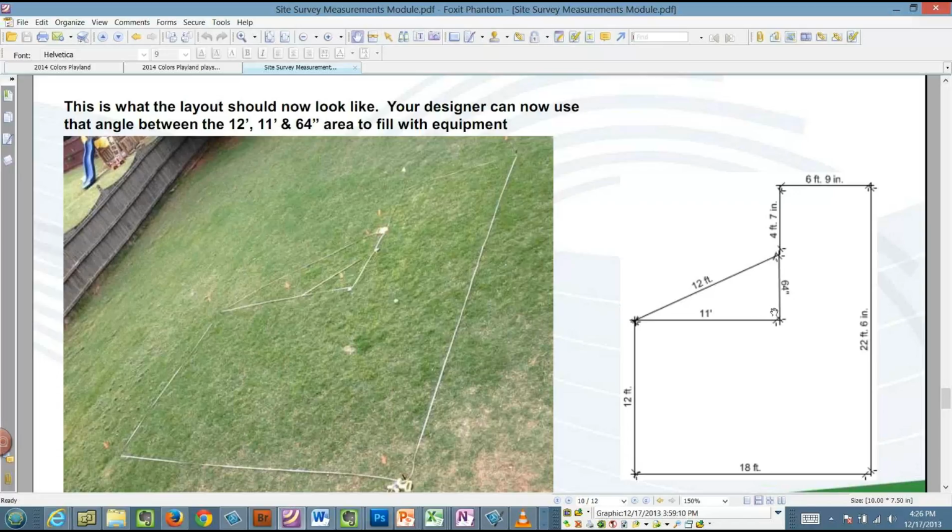You could visualize this if you wanted to, and assume what a 90-degree angle looked like without doing 3, 4, 5, but there's no guarantee. Okay. So if this weren't 3, 4, 5, and these weren't lining up properly, you would find that your measurement could be off. If this were off by a few degrees, you could find that your area measurement might be too short or too long. And again, talking about exacts, and when you're talking about surfacing, those numbers add up.